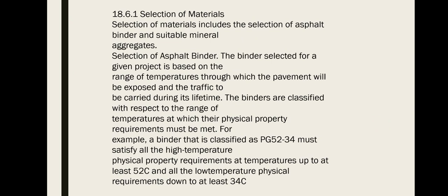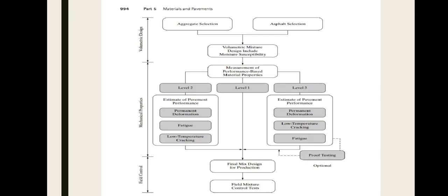Selection of asphalt binder. The binder selected for a given project is based on the range of temperature to which the pavement will be exposed and the traffic to be carried during its lifetime. The binders are classified with respect to the range of temperature at which their physical properties required must be met. So, materials and pavement. This is the field control, mechanical properties, and volumetric design illustration.